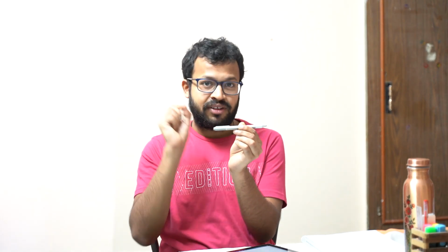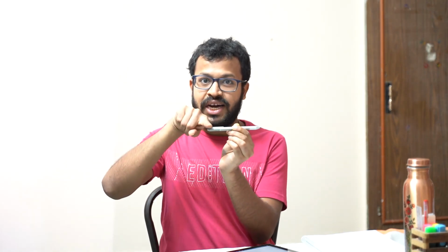So remember that Peclet number thing again. It assumes that if the Peclet number is greater than 0, or if the flow is going this way, the Upwind scheme assumes that the property here is actually being transferred from the capital P point. So it doesn't say that phi small e is the average of these 2 numbers. It is very direct in the sense that it says that phi at small e, or the control volume face, is the same as the upstream side because the flow is going this way. So this is the upstream side, this is the downstream side. So for this particular point, this point is the upstream point and this is the downstream point.